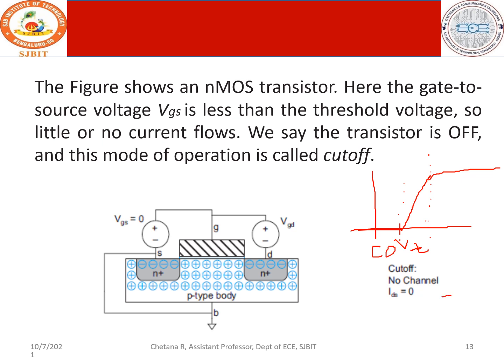The x-axis is VDS and your y-axis is your current ID, drain current. How much current flows depends on the voltage you apply. So this is your linear region. The current and the voltage are proportional. And after one stage, irrespective of how much drain voltage you give, this becomes saturated. This happens with one gate voltage as reference.